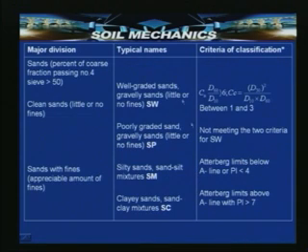Next is sands, the subgroup in the coarse grained soil. Previously, we have seen gravelly soils. Now, similarly with the sandy soils, the percentage of coarse fraction passing number 4 sieve is greater than 50. Clean sands have little or no fines; sands with fines have an appreciable amount of fines, which cannot be neglected. So, well graded sands, like we did for gravels, similarly well graded sands, gravelly sands, little or no fines.